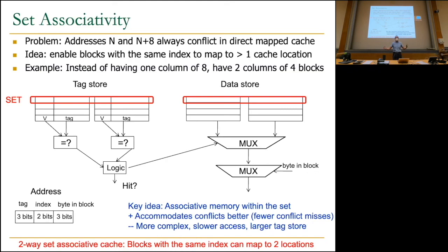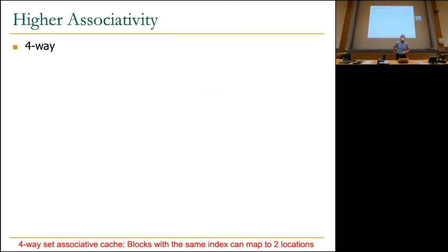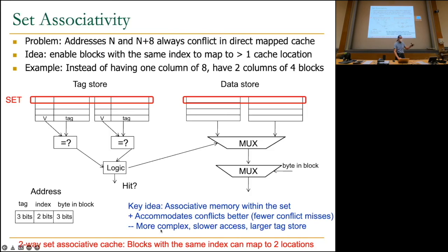That's why a lot of caches today are set associative. In the old times, direct map caches were very nice because we didn't have a lot of transistors, right? This is where Moore's law helped us. Right now we have a lot of transistors, and transistor speeds are faster. As a result, people are able to build higher and higher associative caches. But this is still very fundamental, right? If you increase your associativity to be too high, your latencies and power also increase. I didn't talk about the power, but think about the power of accessing multiple structures concurrently. You drive 2 8-byte blocks out as opposed to 1 8-byte block out. So you're actually increasing the power consumption as well.